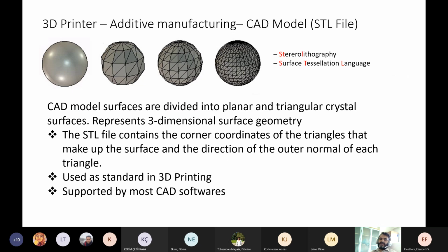In fact, parts cannot be produced directly from a CAD model yet. The CAD model must go through a pre-processing stage. STL format is standard now. In this format, CAD model geometry is expressed by planar triangular surfaces. While we use STL, all rapid prototyping, 3D modeling, additive manufacturing, layered manufacturing, whatever you call it, all of these technologies apply the layer-by-layer production method.